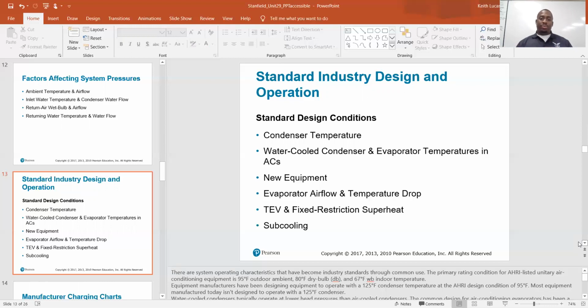And the same thing's happening on the flip side in the evap coil. We need that evap coil to be at a cool 40 degrees because we got 80-degree air coming in. And so when that 80-degree air comes in through the return and we got that 40-degree refrigerant in that coil, that heat transfer is going to take place again.